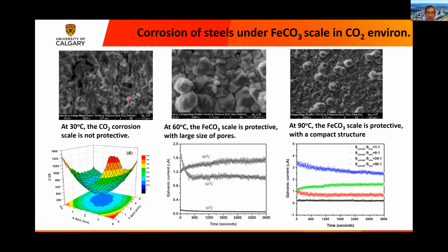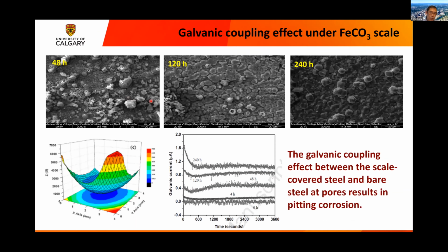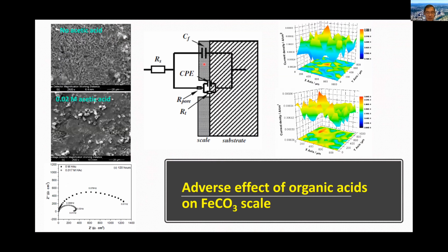We can use localized impedance to measure how different porosity can introduce a different corrosion rate. Typically the porosity is micron scaled. We can use this measurement information to characterize the microstructure of the corrosion scale. And finally, we can establish how this scale will influence further corrosion.